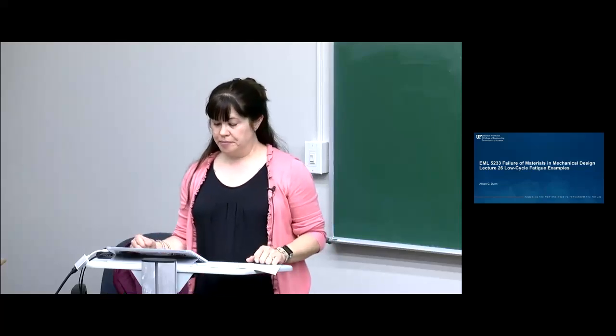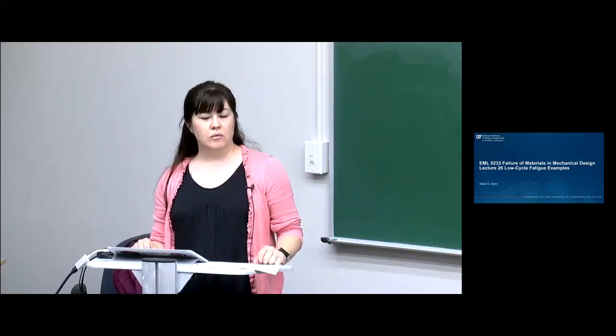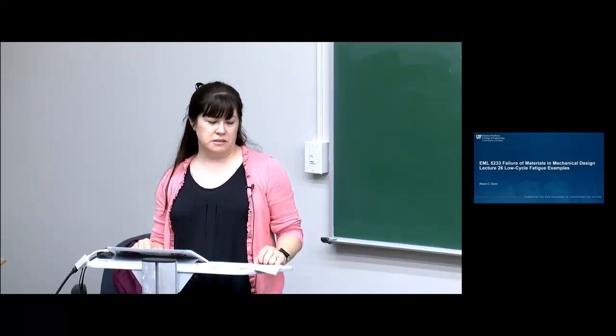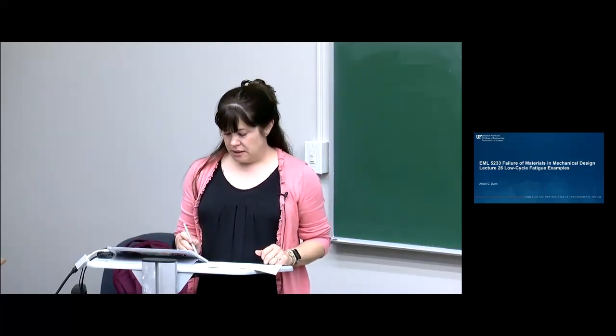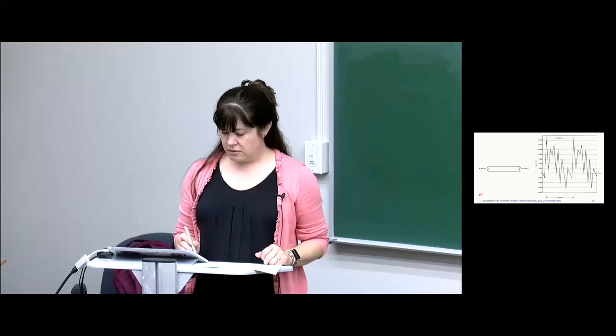The last lecture was about low cycle fatigue, and we basically came up with a strain versus cycles plot instead of a stress versus cycles plot. Because at those really low numbers of cycles, we don't have the stress situation that we had before, when we were doing stress life. Rather, we have something more like strain life, because it was found that strain cycling corresponds more with the life than does stress cycling.